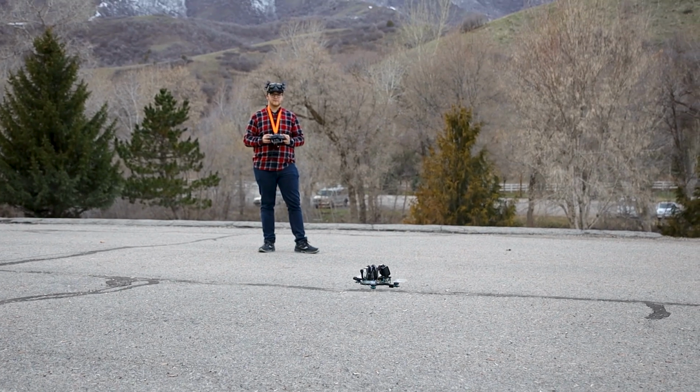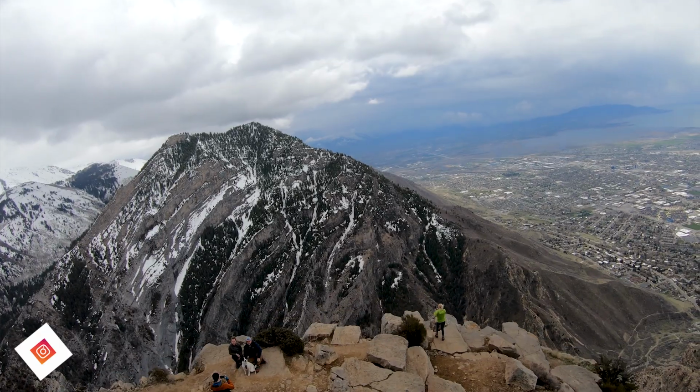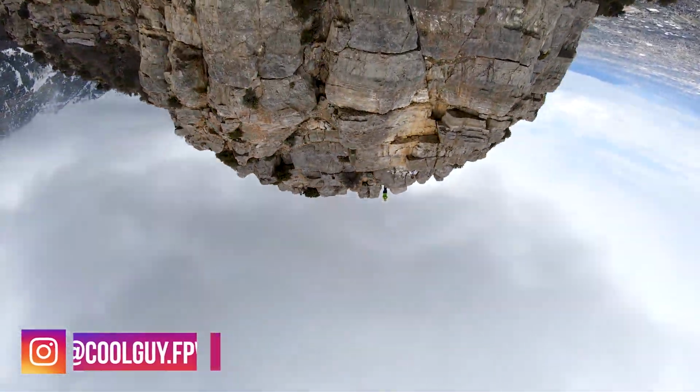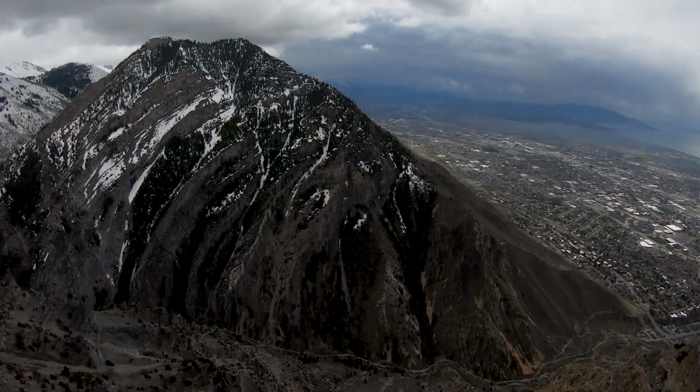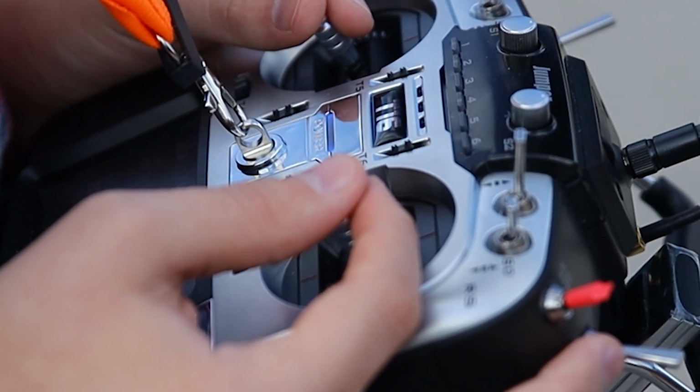Accelerometers and flight controller. Most flight controllers will also integrate an accelerometer, which is another separate sensor chip. Accelerometers can detect the acceleration of your drone and the roll, pitch, or yaw axes. This includes the force of acceleration of gravity, which the accelerometer uses to tell the flight controller how to stay level with the horizon. This is used for flying a quadcopter in horizon or stabilized mode, which keeps the quad at a level orientation when the sticks are centered.